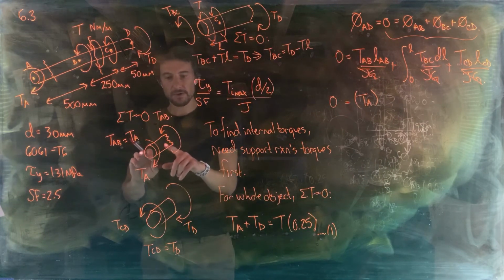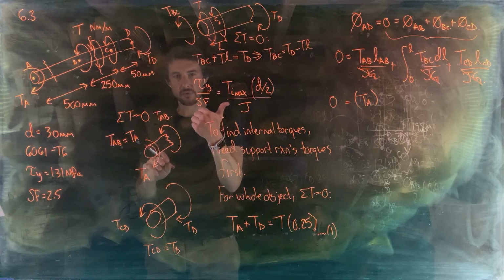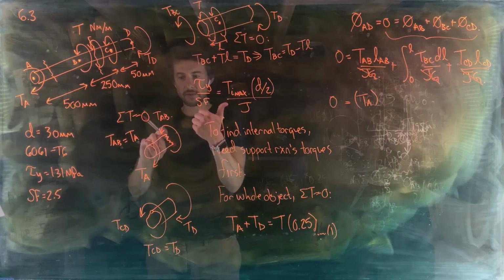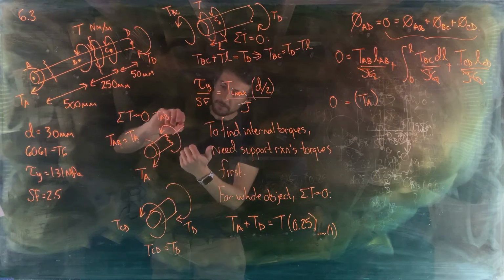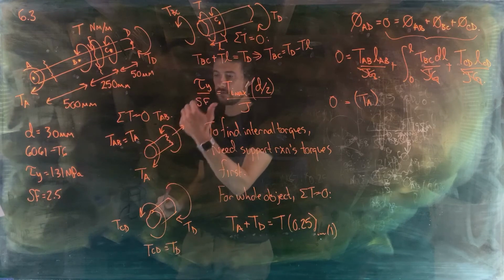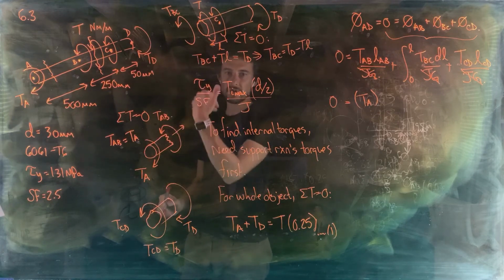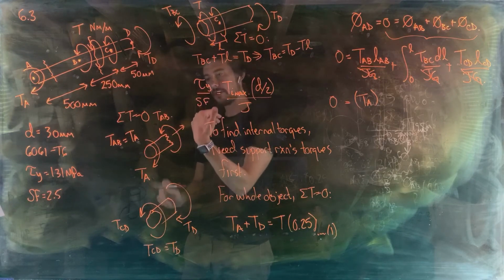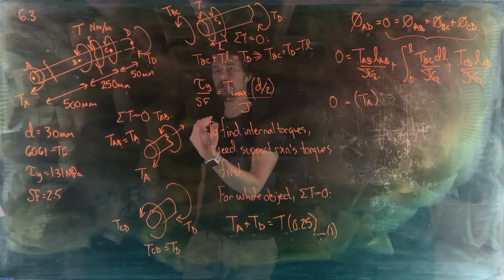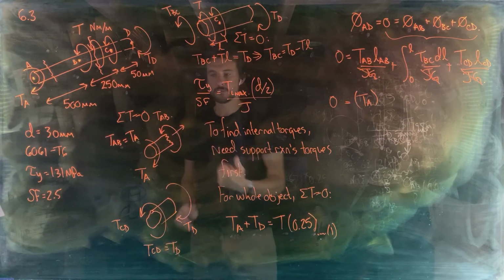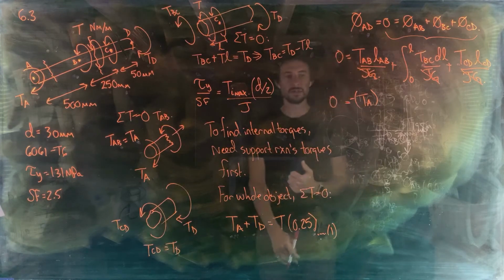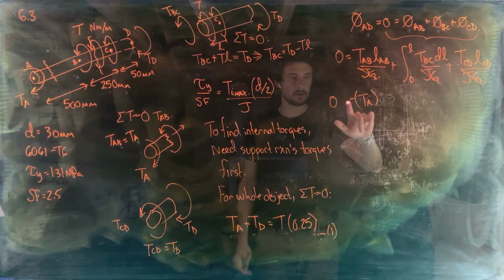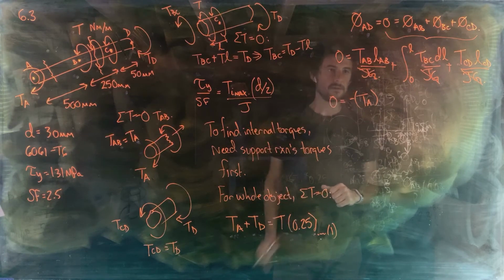So you go over to your free body diagram and use your right-hand rule to determine whether TAB is a positive or negative internal torque. Thumb points out of the section cut in the direction of the arrow. Fingers curl in the direction of a positive internal torque. They're curling in the opposite direction that I've drawn TAB in. So this needs to be a negative when it goes in that equation. Okay. So we've got negative TA there.